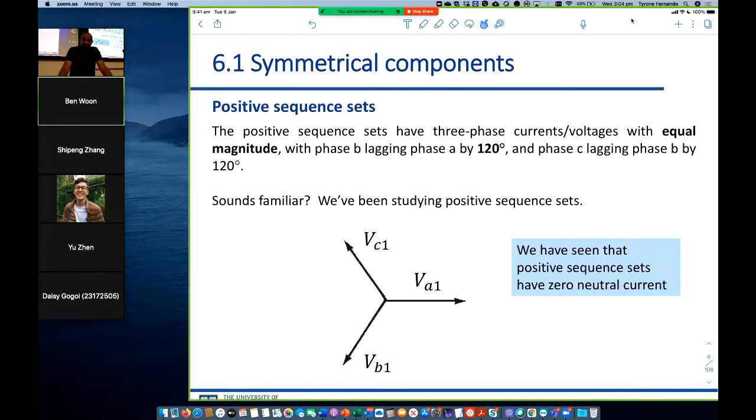So we're talking about a positive sequence voltage set. All the magnitudes are the same, and they just differ by the phase angle. We've seen that sequence when we talked about balanced 3-phase systems. In the sequence ABC, B is 120 degrees behind A, and C is 120 degrees behind B. So the 3 separate phases have the same magnitudes, but they differ by the phase angle.